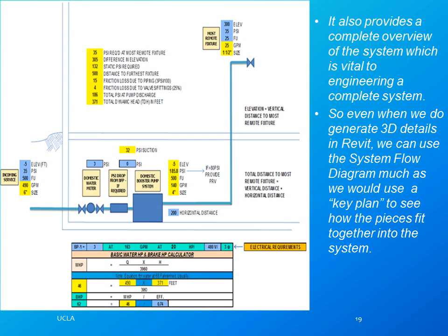The third pump rarely, if ever, will even run. But we need to make sure that we have the pressure to get up there. So we designed the pumps to have the GPM split between the number of pumps, but the pressure to be the same for all the pumps so that one pump could provide enough pressure to get to the top at the reduced flow.